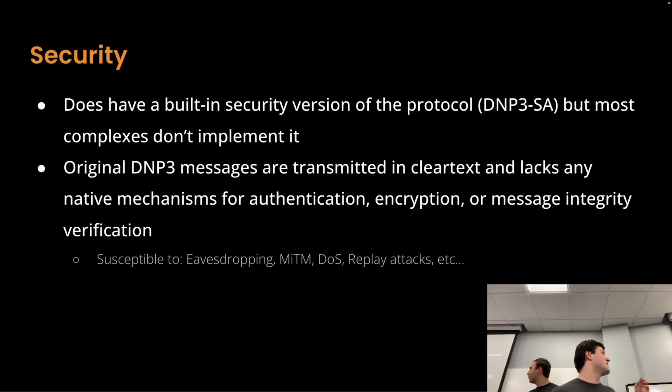And the original one is just kind of like Modbus. Security-wise, it's all in plain text. There is no authentication, and it's susceptible to pretty much any cyber attack that an insecure protocol is susceptible to, like eavesdropping, man-in-the-middle, denial of service, replay attacks, etc. When it comes to actual attacks, no one specifically notes DNP3 in malware reports, so it's hard to know which ones have actually been used, but it is widely used in critical infrastructure, especially electric grids.